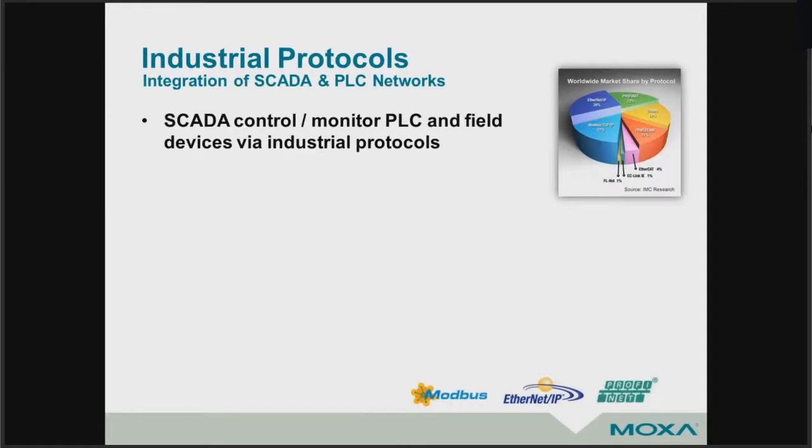And if you've got multiple industrial protocols running in a factory environment, there are many industrial switches out there that will allow multiple protocols to run on a single network. If you've got that, you probably want to investigate that.